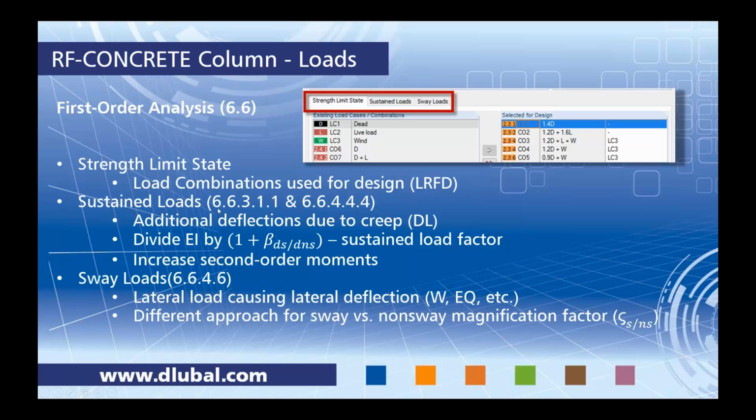Now, sustain loads. This comes from section 6.6.3.1.1 and this other section here. And this just tells us that we need to take into account additional deflections due to creep. This doesn't necessarily have to be a gravity load, but this could be a lateral load as well. Typically, you'll find things like dead load are something you want to consider for creep. And that's where we would add this into the sustained load, something like our load case dead load.